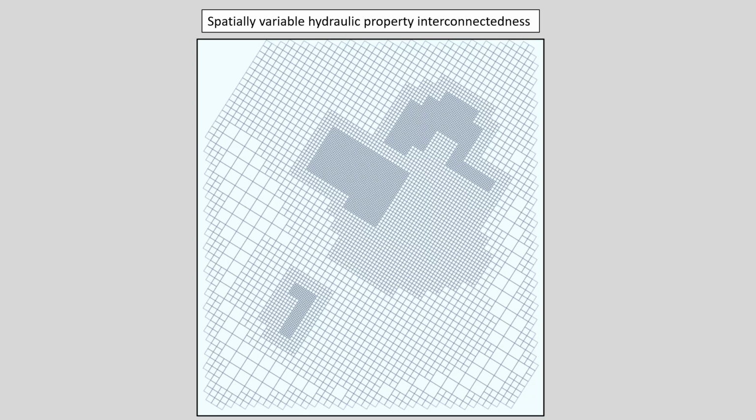So here's a model domain in which we've placed an unstructured grid, and perhaps the outcomes of site characterization suggested something in one part of the model domain. We've got spatial correlation lengths shown by this ellipse, this distance in this direction and this distance in the orthogonal direction. Perhaps things are the same here, but not here. Perhaps in this case the direction of anisotropy has shifted, and indeed also the correlation lengths in different directions may be different.